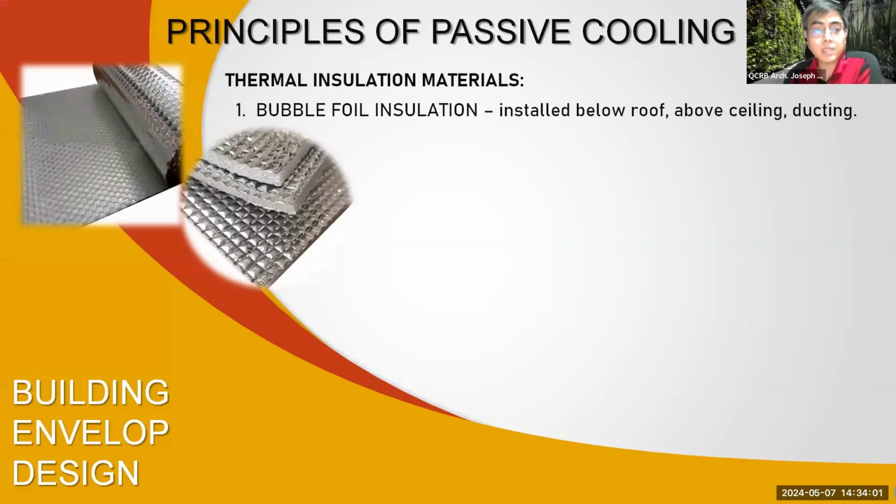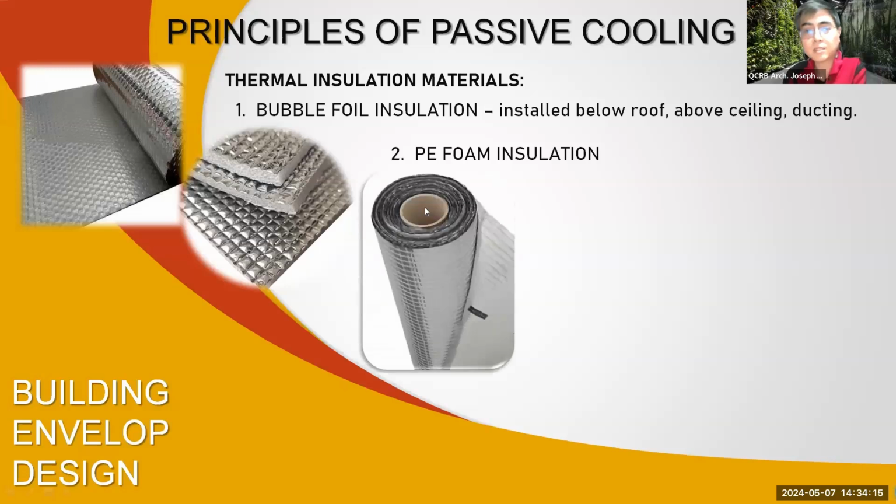So it's basically parang styrofoam with aluminized, or usually ito is aluminized foil, no? Hindi siya actually aluminum foil. So parang plastic siya na may aluminum coating. So it actually degrades in time, no? That's a PE foam insulation. And then there's a third, that's aluminum foil membrane. So the third one is merely aluminum foil lang yan with wires, no? So actually ito yung pinakamatibay.